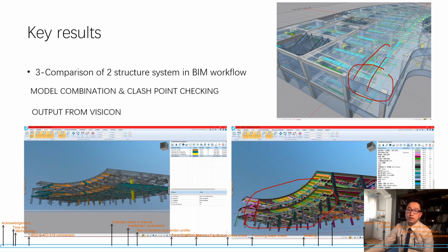And in the display mode, we can obviously see that it's more comfortable than Navisworks. So the location of the clash point is clear. We can customize the color of the clashing point. It also has the ability of setting the degree of tolerance in model combination. So this is very applicable in solving clashes.